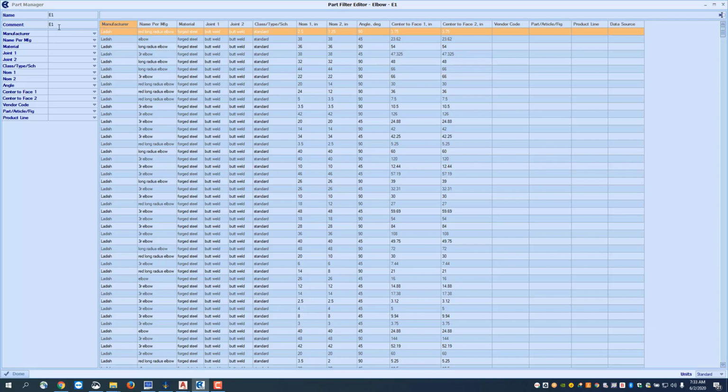But I'm going to come over here and give it a name. In this particular field, I'm going to put up to 2 inch, because I'm going to use malleable iron fittings up to 2 inch. In here, I'm going to put in the manufacturer's name. So I'm going to say this is going to be my Anvil 150-pound malleable iron fittings. Now, every one of these other fields become filters.